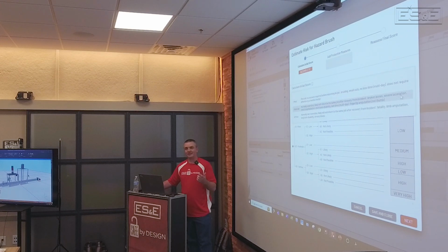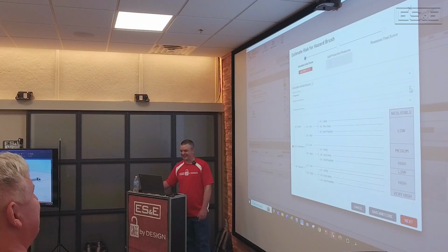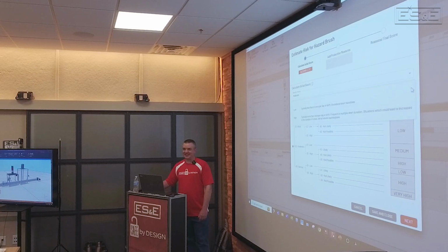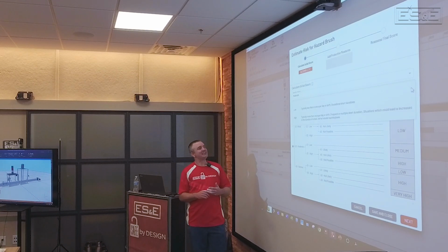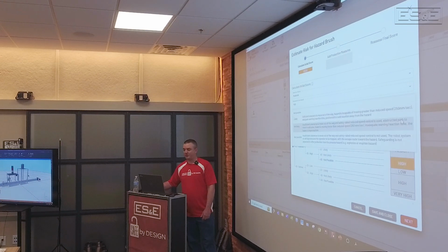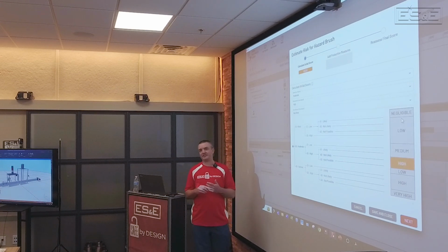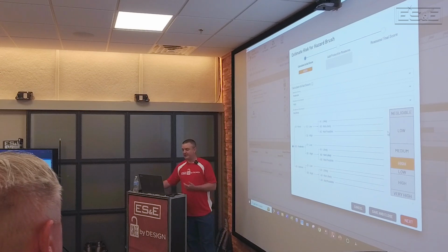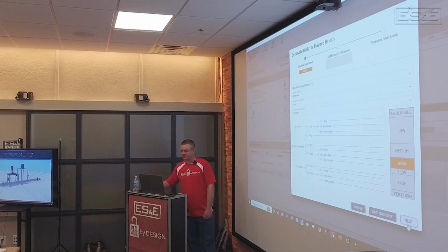So again, if your hand or my hand gets tangled in that brush, I'm going to consider it a moderate hazard. Your hand. I prefer your hand though. Exposure to the hazard: high. Definitely high. Chances of avoidance: not likely. And like I said, even with not possible, you can see it doesn't change our outcome. But either one of these choices is really based on the standard when you look at those definitions. Either one's going to drive us to a performance level D type system.